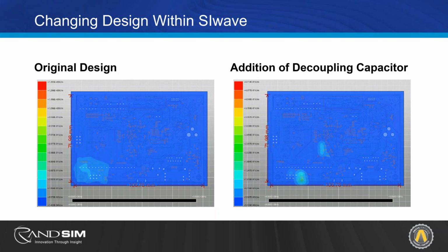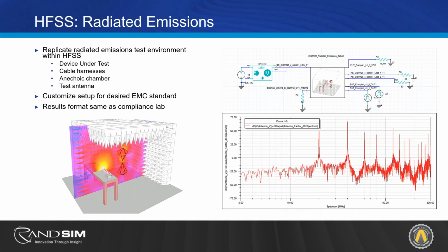And that's the end goal, is to catch as many of these things before you actually have to make the board and get it spot checked to see if it will pass. And that brings us into the next phase. So what I've been talking about has been predominantly hosted in SIwave and is the most effective means of evaluating for EMI, because it pinpoints all of the different sources, potential causes, and means of radiation.